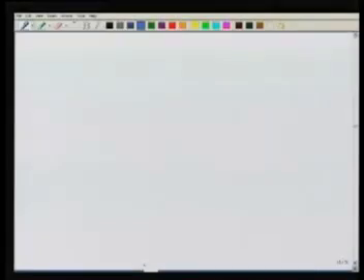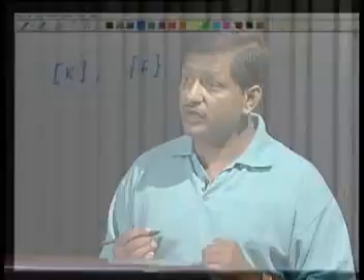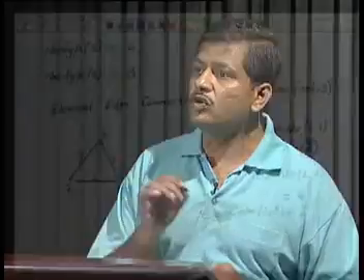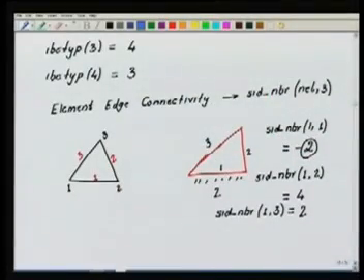So the next step is that, okay, we have obtained the element stiffness matrix and element load vector. Now what do I do? I will have to assemble them to obtain the global stiffness matrix and load vector. So the global stiffness matrix will be K global and the global load vector will be F global. For that, again I need to construct the information which tells me where the element degrees of freedom go globally, that is, which global degrees of freedom they correspond to.